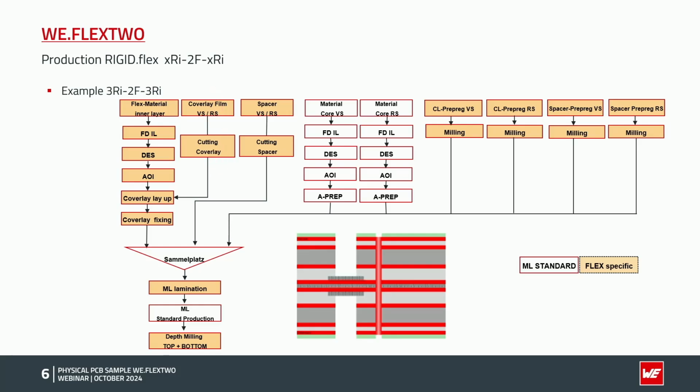So we have to cut the coverlay. We do this by laser or by a cutting tool, and we have to fix it on the polyimide on the flex in the flex area. On the other side, we have to route the prepregs. You have to do it for the prepreg, sorry, and for a spacer used in the flex area to prevent